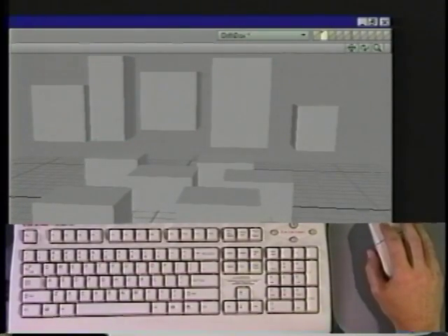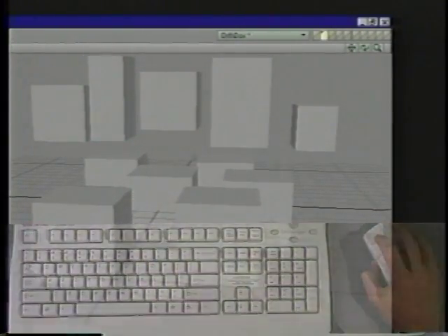And you'll see I'm getting quite a collection of boxes here in my perspective view. And remember though that this last box here that I dragged out, the one that still has sort of the highlights around it, that basically means that box hasn't really been created yet. And if I don't drop the tool, that box will just go away if I start doing something else. So I want to go ahead and create that box. I'm going to hit the space bar, and there that box will stay there. Okay? All right. So our interface is quite messy here. So I'm going to get rid of that.